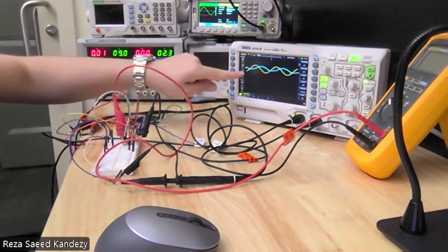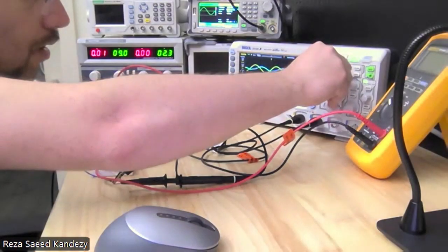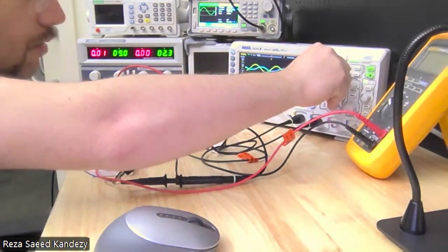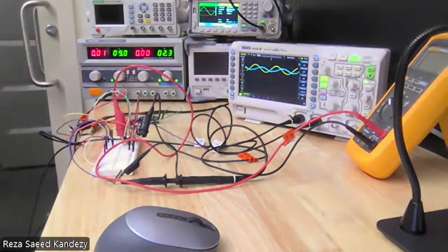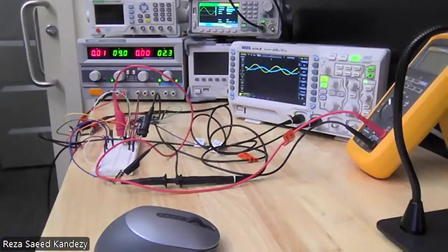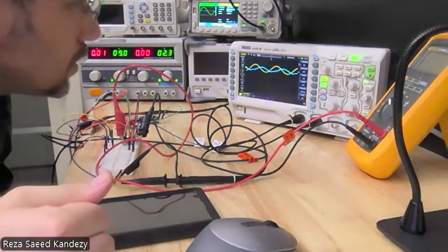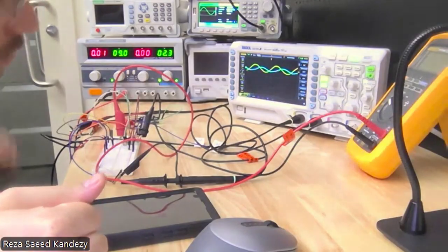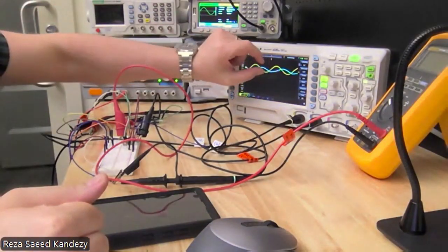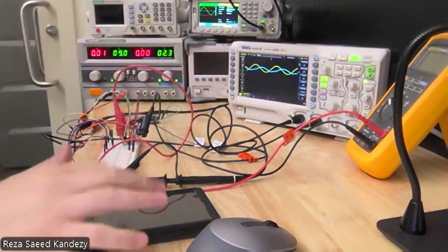Now, you see, let me do a little bit better. Based on my measurement in our oscilloscope, my input voltage is 1.5 squares in my grid, and the voltage division for my channel 1 is 2 volt.